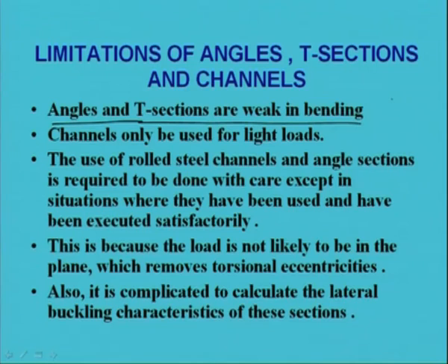We can see that from experience, the angle sections, and of course, this is not symmetric. So, when the bending moment occurs, because of unsymmetry, we have to see what stresses are happening in different cases, and accordingly we have to design. So, in general, angles and T sections are weak in bending. Another thing we have observed is that channels can only be used for light loads.